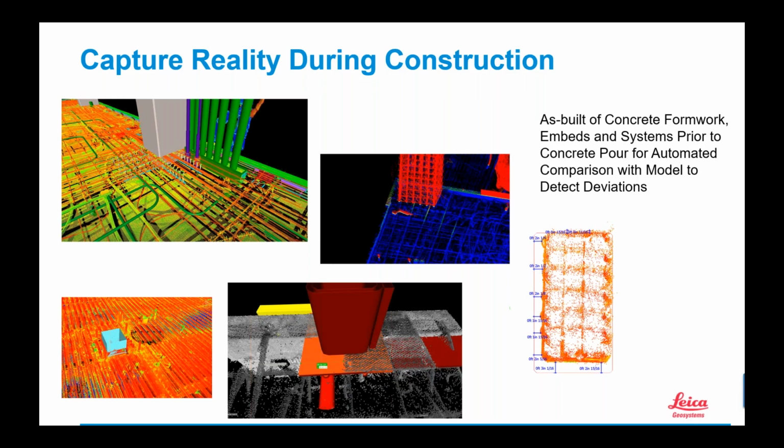before the slab is poured, or before that wall is completed, before that structural column is poured? That way, if I need to mount a jib crane or some type of crane from that column 10 years from now, I can always look at that data, see what's in that column, or see what's in that wall, or see what's in that floor, know exactly where the conduit or the pipe sleeves or pipe are. Say there's some type of piping system running in the slab. I know where all of that is. It's documenting that as-built condition. All right. That is extremely valuable.